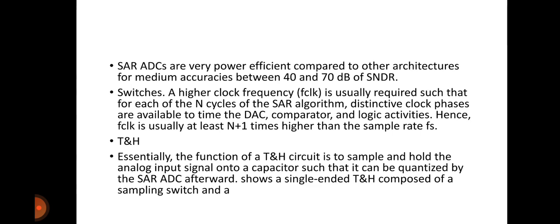Essentially, the function of a T and H circuit is to sample and hold the analog input signal onto a capacitor such that it can be quantized by the SAR ADC. Afterward, it shows a single-ended T and H composed of a sampling switch.